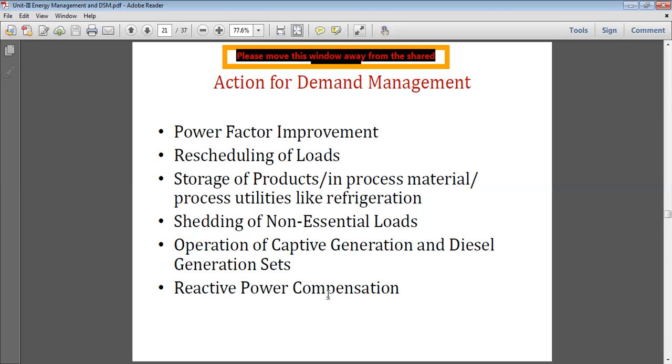and these are less priority feeders. Okay, so this is called, say for example our college also, it is not necessary to run the power for our pumping system during 10:30 to 12. It is always found that as soon as the college starts at 10 or 10:30, people come and they will start their load, including the pumping system and the garden pumping. So instead of that, we can shift to the night time, to the off-peak period, and hence we are able to reduce our maximum demand.